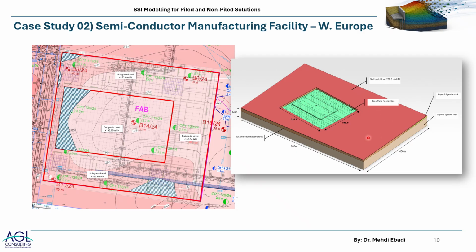When we have several boreholes, in this case, as you can see, in 400 in 600 meter area, you have several, and in plan you can see, then the program interpolates each layer based on the immediately adjacent boreholes or rotary core holes, or in terms of the program definitions, the layers that we define.